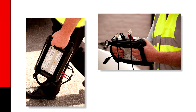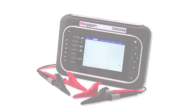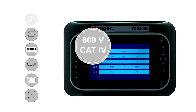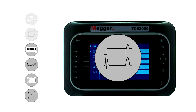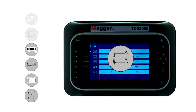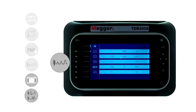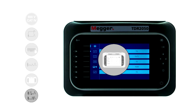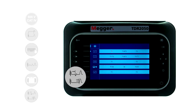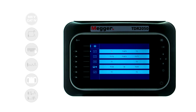The Megger TDR2050 is a dual-channel, dual-trace TDR with a high-resolution colour screen for locating faults on paired metallic cables. The instrument has Cat4 600-volt input protection built in, step and pulse TDR options to see both near and far-end faults, trace tagging for recording circuit ID, distance-dependent gain to minimize signal attenuation, a trace hold feature for instant trace comparison, auto-find and find-end functions allowing speedy fault identification.